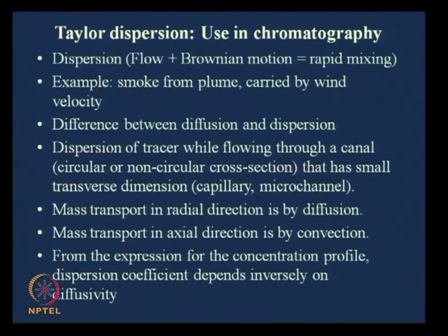Next topic that I pick up now is known as Taylor dispersion. You remember when we were talking about that on off mode of mixing, there, instead of a diffusion coefficient, I mentioned dispersion coefficient, and instead of D I have written D star. There is a reason to it. When we talked about a spot of tracer diffusing into an infinite medium, we restricted ourselves to diffusion coefficient. However, when there is a flow as well as diffusion, then we have to take some additional terms, and then we call this process dispersion rather than diffusion.